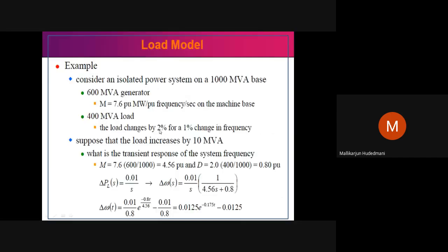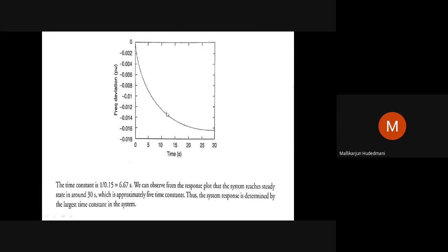Now you can see this problem compared to the one you have seen. It was declining in the earlier problem, correct? Coming to steady state easily. This way, it is rising because of load rejection. There is a deviation increasing. In fact, we want to bring it to frequency deviation 0. But here the load is suddenly removed by 10 megawatt. Then frequency has to be controlled to a steady state error equal to 0. This shows how the dynamics of this load is experienced by the power system operation and control.